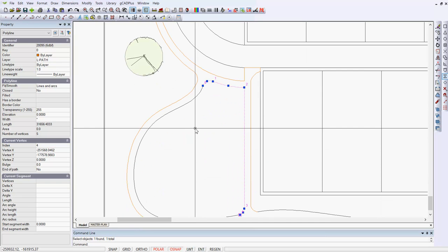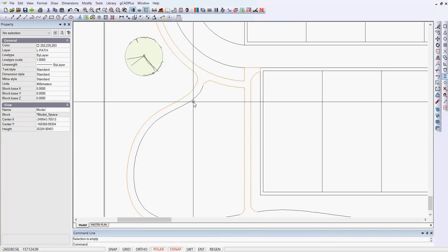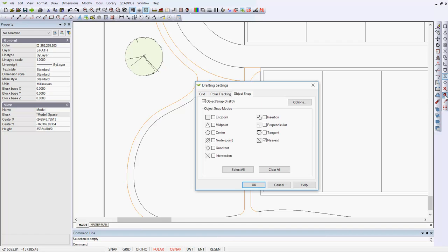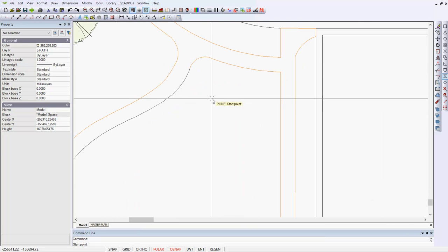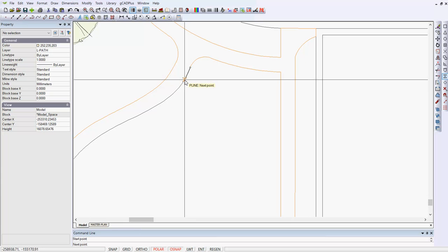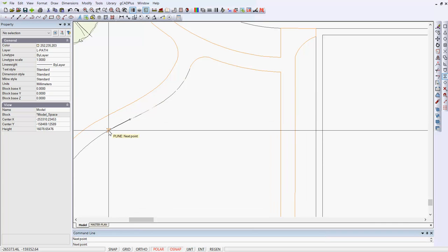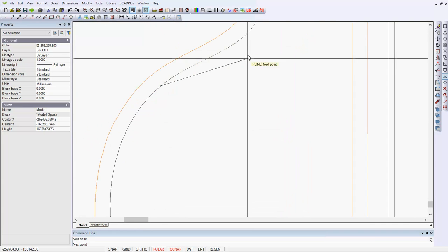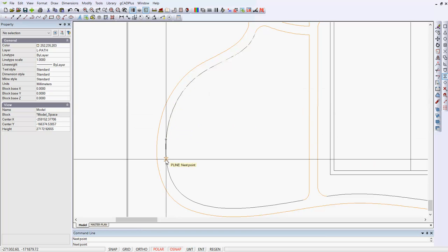May well be a grassed area. The easiest way, since the geometry is already there, the easiest way to improve your drafting is to go to Object Snap Settings, turn it on and pick Nearest. That means that I can go Draw and Polyline. I can start by an override and pick up the end of that section, and now because I have Nearest on, I can just trace my way around the existing shape. That will save considerable time.